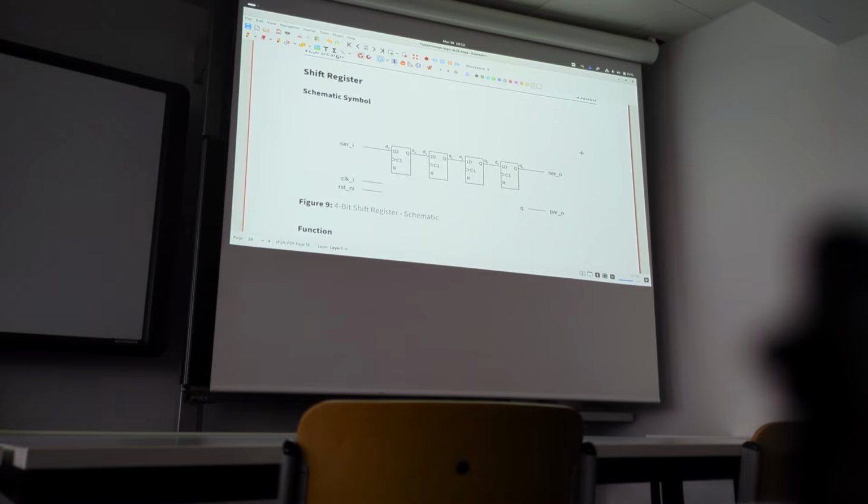A shift register is always needed because nowadays we transfer data, we work on parallel data, we have to serialize data to transfer it over different communication channels, and we have to receive the serial data and parallelize it again. The central key element actually is a shift register.